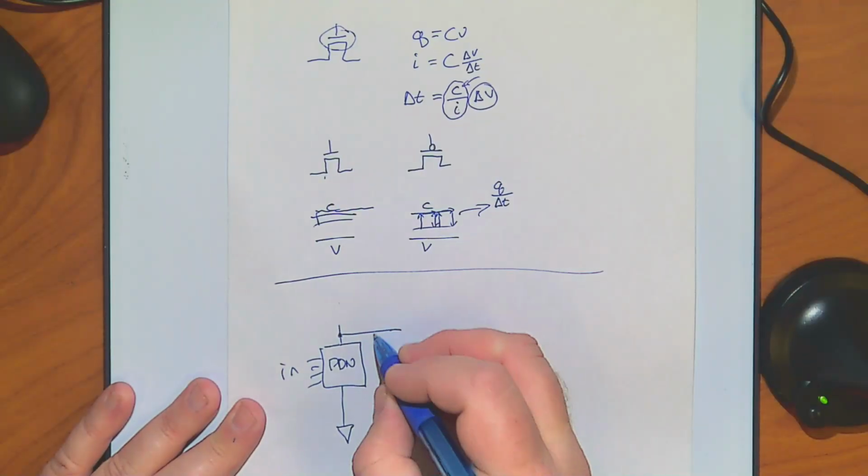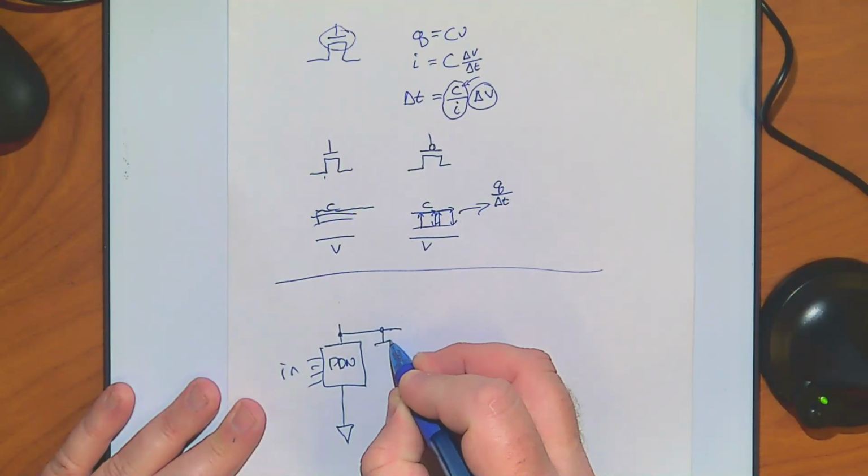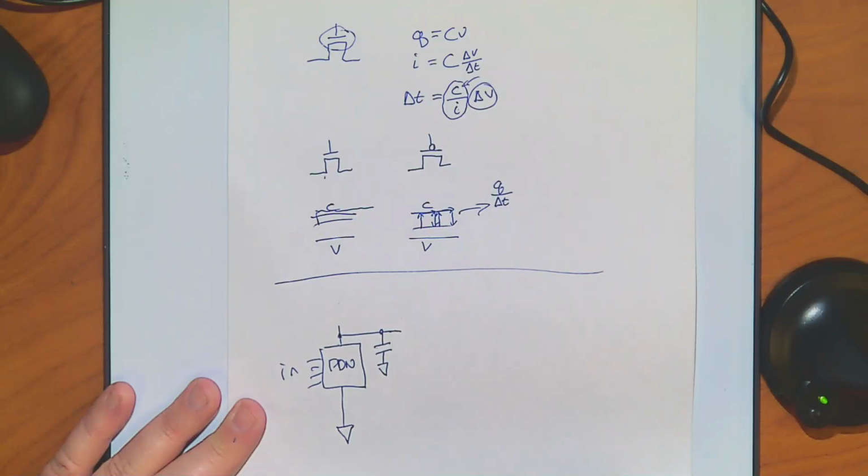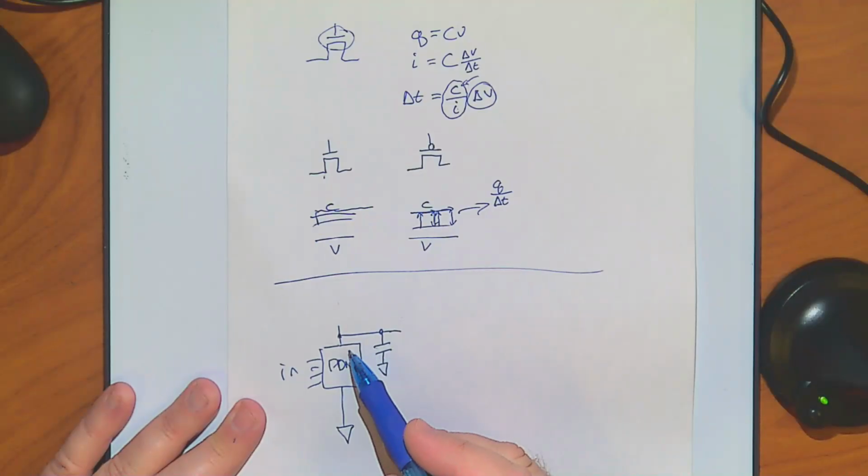A capacitor could, right? What if I had a capacitor here on the output? And say, for instance, this capacitor was charged. We'll figure out how to get it charged in a second, but let's just assume it's charged for the moment. So if this is charged, and this says, okay, hook me to ground, give me a 0, that capacitor will discharge and you'll get a 0, right?